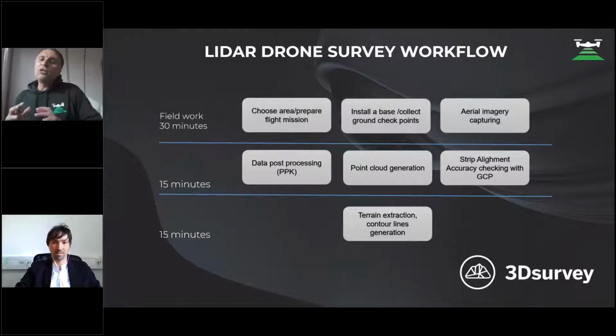But of course, you need to colorize point cloud. In this case, you need to make steps of photogrammetric data processing as well. You need to get images with high precision coordinates inside, and after that, make air triangulation and colorize point cloud. And if you combine both data sets together, you will get very detailed and amazing results in the future, and you can make maps, very detailed maps and vector layers with using of both data sets as well.